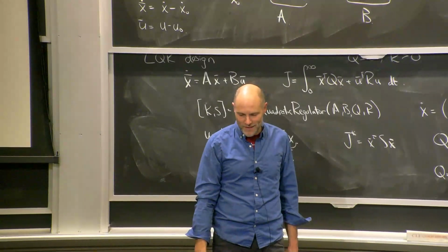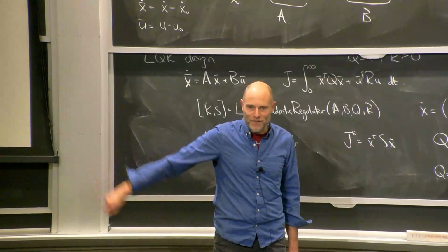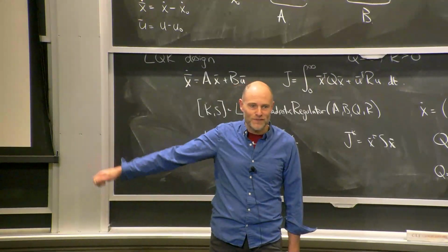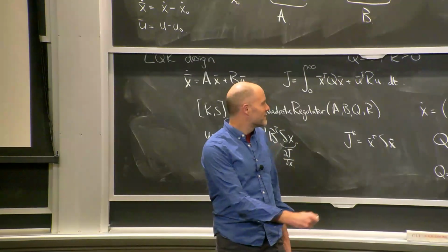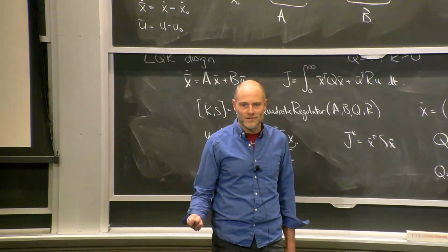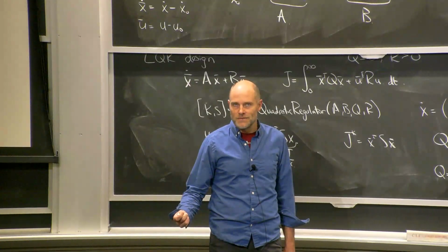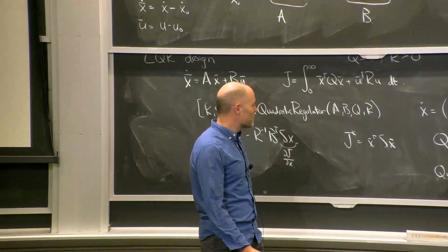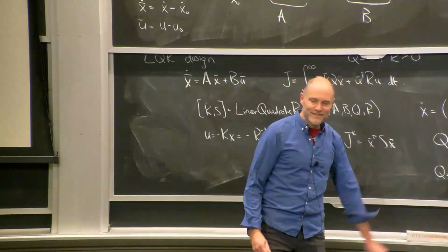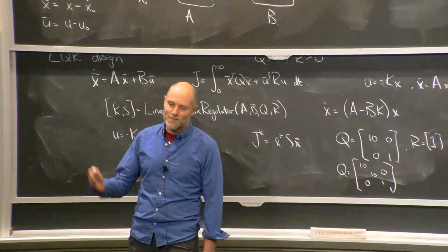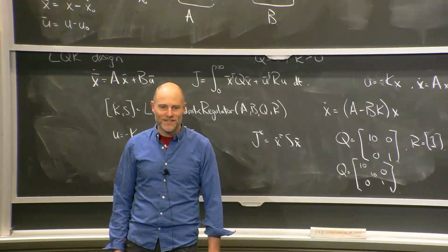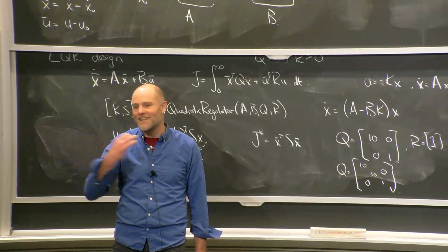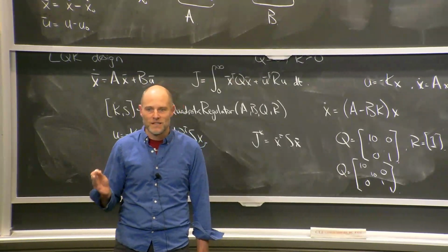I don't know. So square root of G over L. If I have a pendulum that's roughly a meter long in a gravity that's roughly 10, then square root of G over L is square root of 10, because I get a thing that's 10. So if your robot's a meter tall, then this is a great scaling. And all my robots are about a meter. Well, they're not a millimeter, right? They're closer to a meter than any other thing. So I just use that as a rule of thumb.